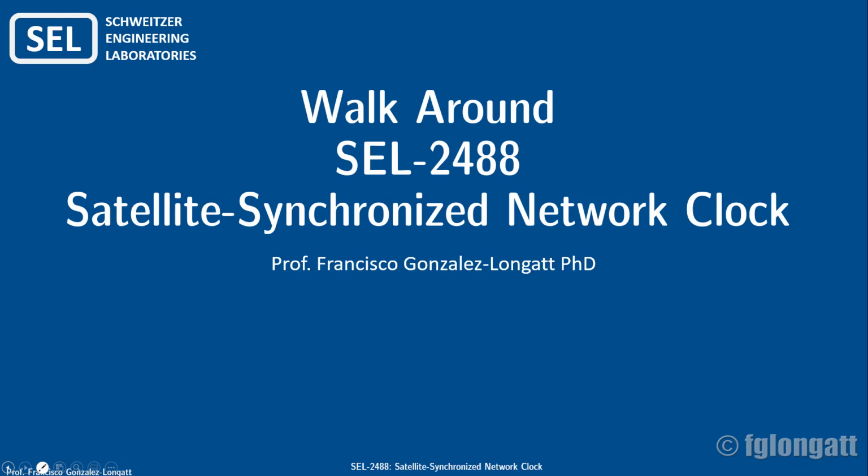In this very short video, I explained what is the motivation behind using a very precise clock inside power systems. Inside the substation, we need this clock in order to define timestamp. That timestamp will allow us to synchronize all the measurements, and as a consequence, all the decisions, control actions, and protection actions will be on the same time frame.